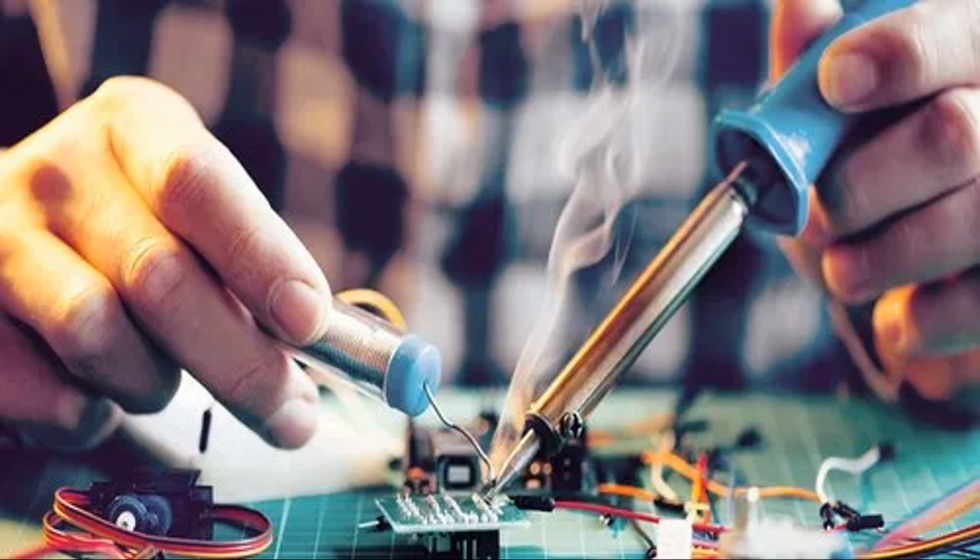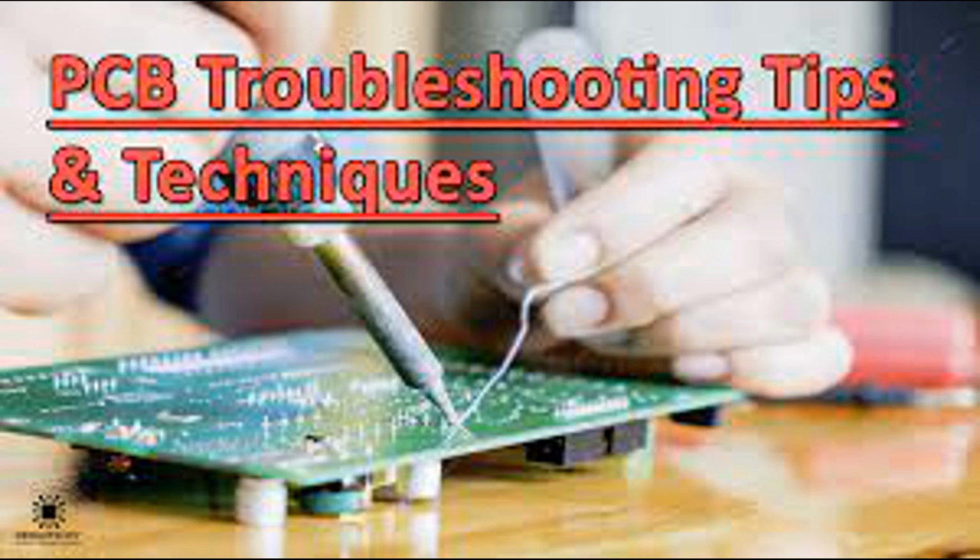Solder mask is typically applied using a liquid photoimageable solder mask, LPSM, or dry film solder mask, DFSM. The application process involves exposing and developing the solder mask material to define the desired areas for solder mask coverage. The areas to be protected are masked, and the remaining solder mask material is cured or hardened.